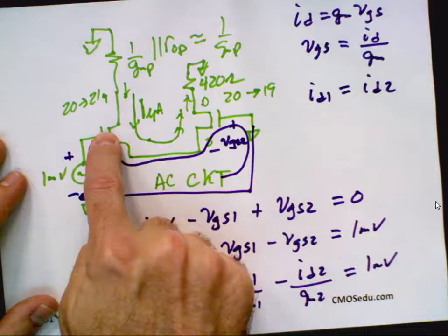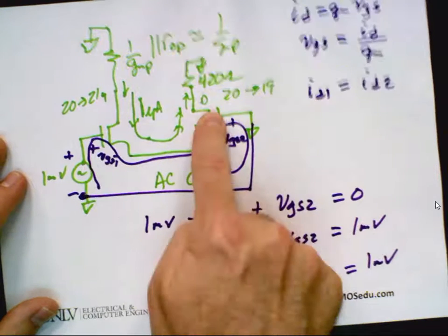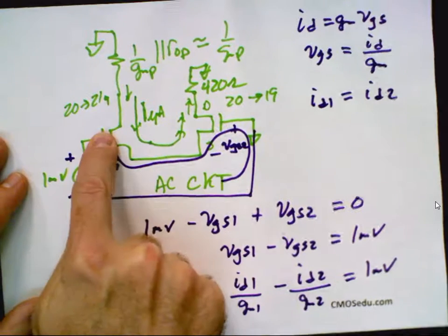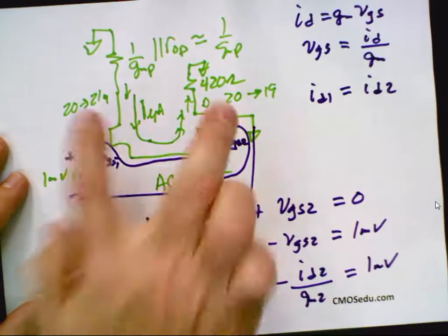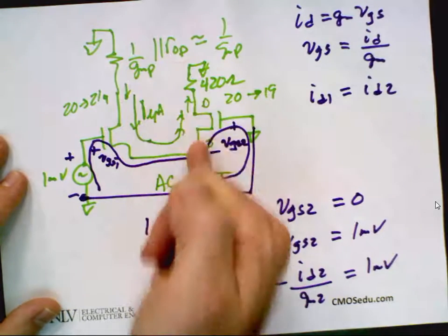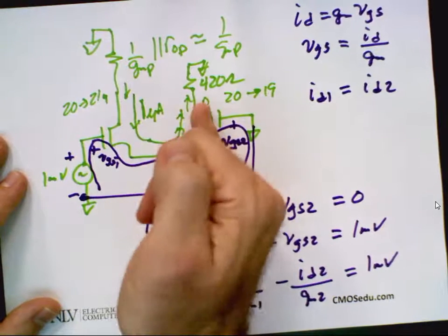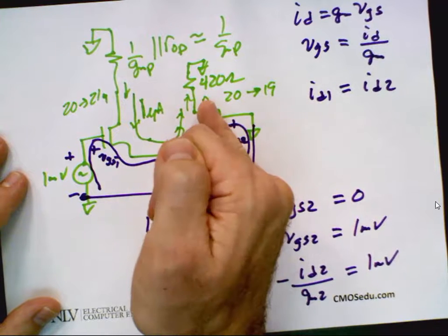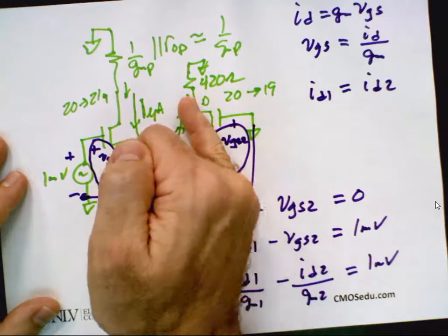This goes up by a microamp, this has got to go down. This one goes up by 2 microamps, this has got to go down by 2 microamps, because they always have to sum to the constant current. A decrease or a negative current in here means an overall decrease, going from 20 to 18. An increase, 20 to 21.